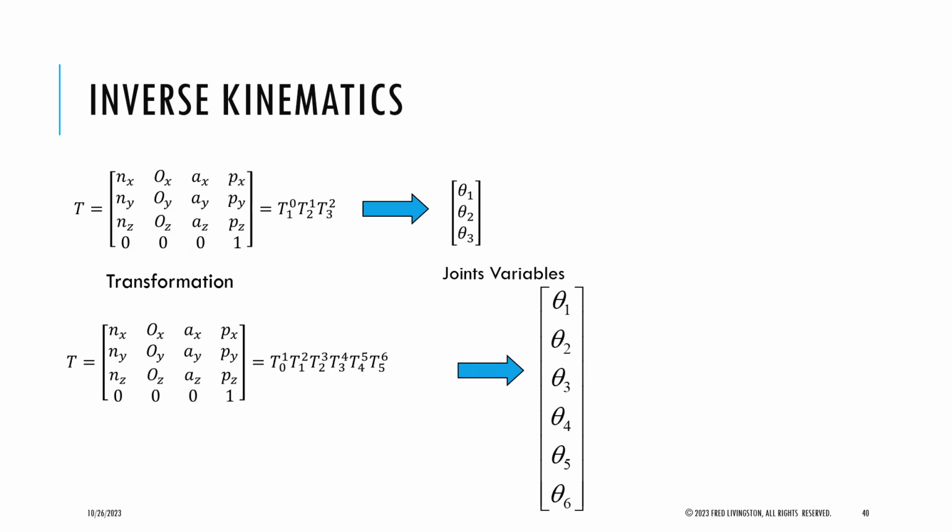And I'm going to set my end effector, which we can call E, to my object H. In this case, it's not physically possible to do that, so it won't converge on a solution, or it may give you a solution that's invalid. So you need to also check. Once you find this Q1 and Q2 to give you that position, and once you've computed that, you need to verify that you can actually reach that position there.